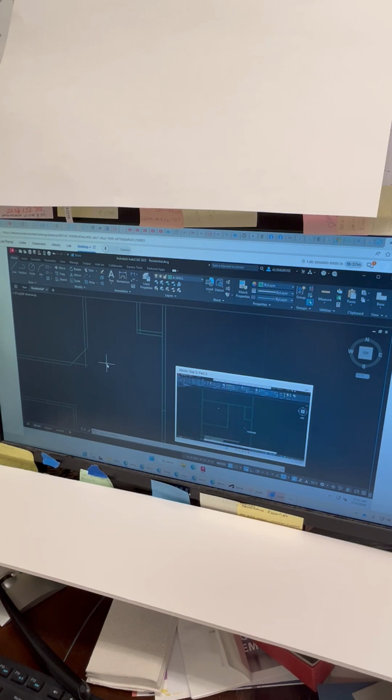Now, select this line, this outside line here with your pick box, and then hover, don't click on it yet, but just hover over this bottom line. Look what you get. You get a preview. So it lets you know that you're doing what you mean to do. That's the result you want. Once you're satisfied, you just go ahead and click on it, and you've now offset that element.